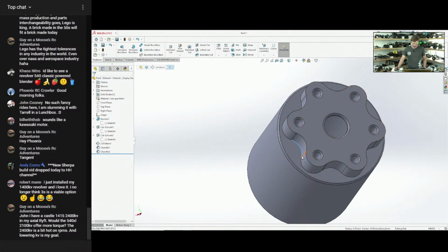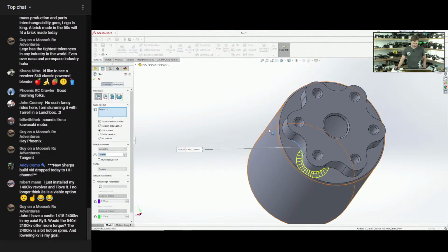It's really easy to overheat the tips. And besides that, they're still going to have a little bit of radius, whether it be 5 thousandths of an inch or whatever. But I know that the machinist is probably going to want to use a 3 millimeter ball nose to clear off this face. I mean, that's what I would use if I was a machinist.